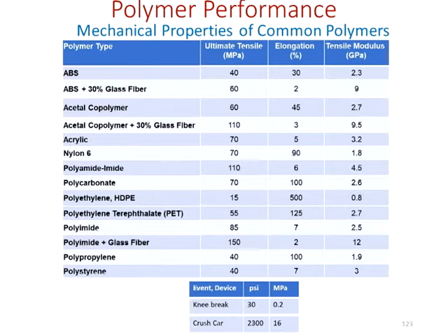Elongation is decreased by adding the fibers to that as well. And we see the same thing in the polyamide. When we add the glass fibers, the polyamide goes down in terms of its elongation. So you start to get an idea of how these other properties are affected by that.